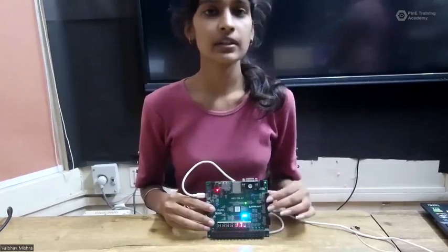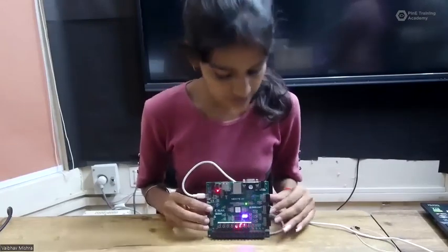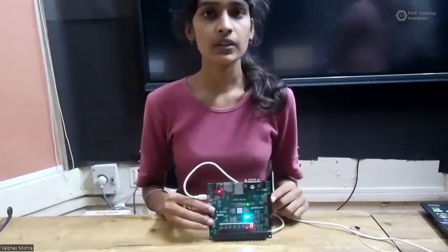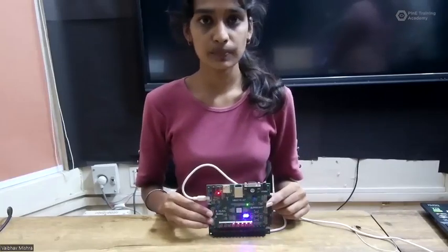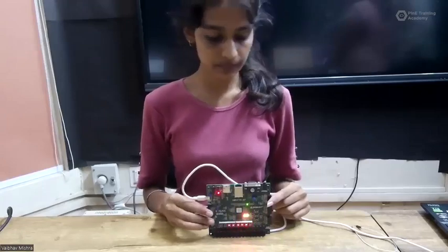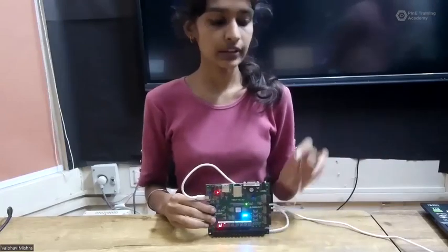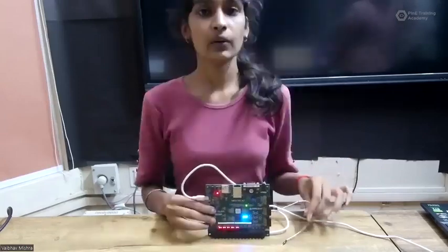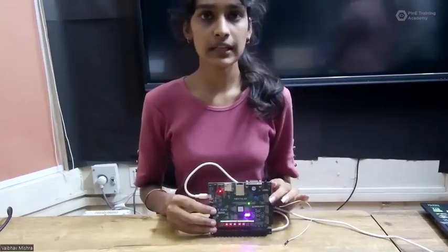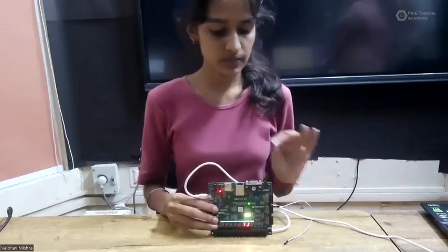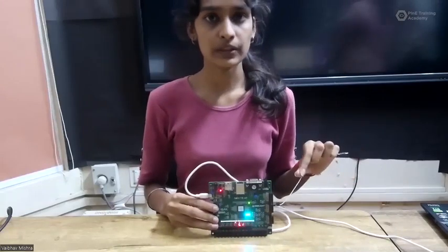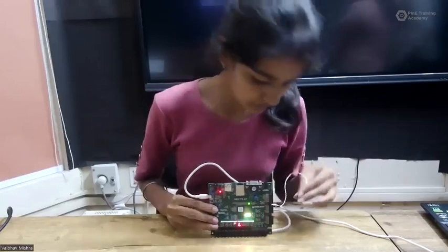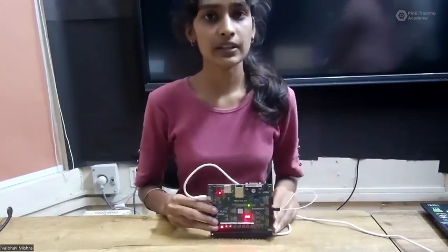For this, there are a total of five jacks of PMOD ports. These 1, 2, 3, 4, and 5 are provided. These jacks have multiple serial communication pins along with ground and VCC pins. By taking a jumper cable, we can connect one end of the jumper cable to any pin of this PMOD board. Now, whenever we give input at the switches, our data is transmitted through this end of the jumper cable. The other end of the jumper cable is connected to another pin of the PMOD board. So from the other end, we can receive our data serially.